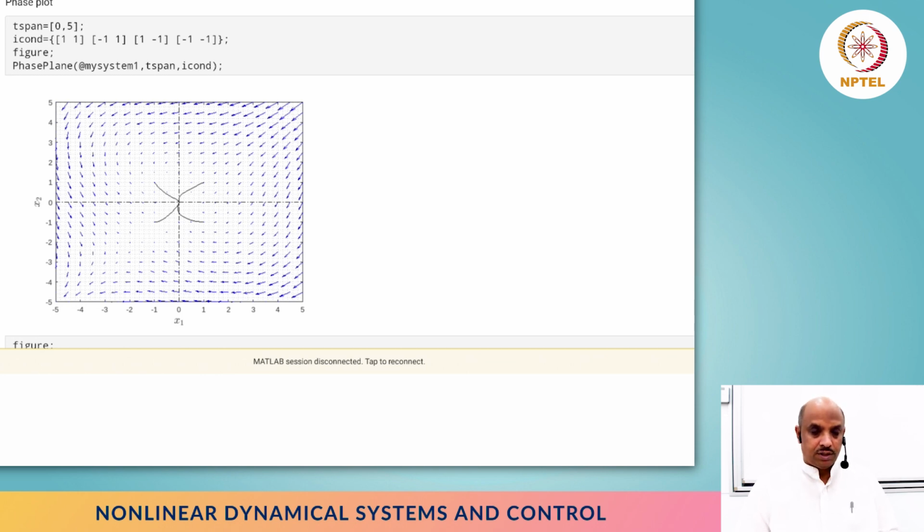And one of the key things, I'll leave that as homework for all of you to do, the MATLAB examples. What is important for you to realize in this particular case is, in all these examples you'll see stability locally, whereas when we try to expand it, in some cases you may not have any issue, but in some cases you will start seeing unstable behavior. So linearization, as much as it's great, the behavior can only be shown locally, but it has also limitations.